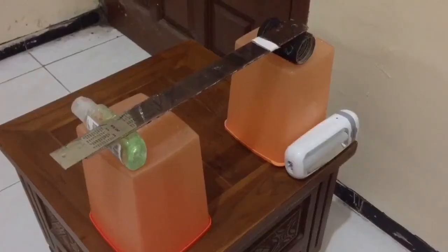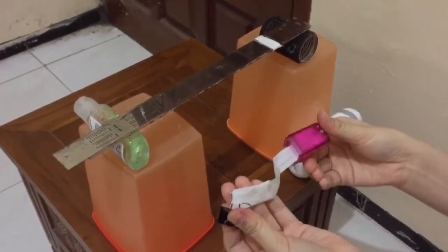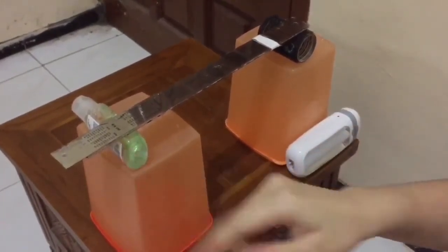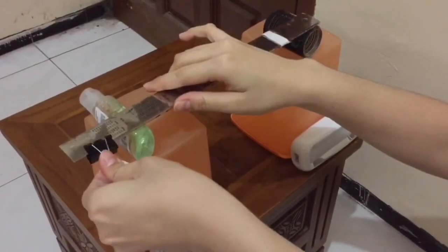Next I will explain the procedure for how to conduct the shear force experiment. Let's assume that these are our equipment, where this is our beam with supports on this side, point B, and this side, point C. And we have a cross section here at point D, this white line here. Firstly, we have to make sure that the display meter is set to 0. After that, we apply various loads at various positions. First, we apply a load of 100 gram mass, 40 mm away from point A. Let's try to put it.